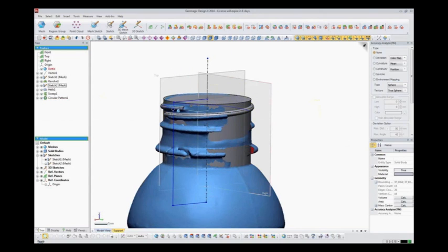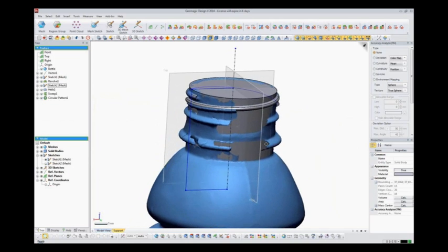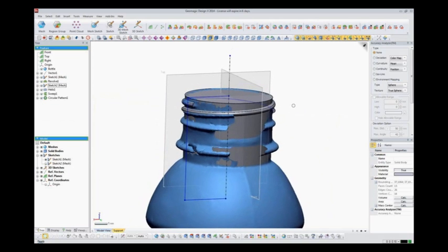So pipe modeling, we just extract the pipe if it's more than 180 degrees of the diameter visible. Then we just extract the pipe line. This is similar to this helix flow, and then we just use the sweep function to generate that pipe. Or we use an extrusion, and then we use a revolution to reflect a specific pull turn bend method.